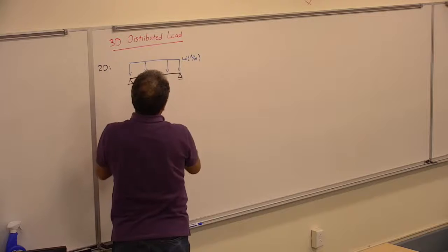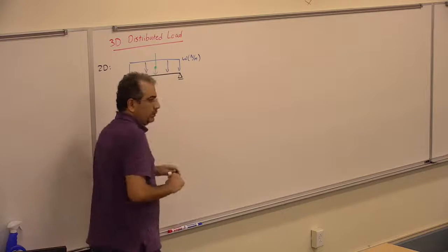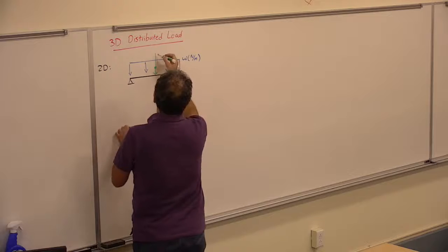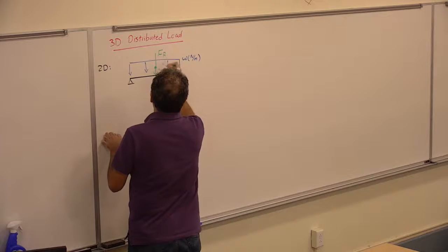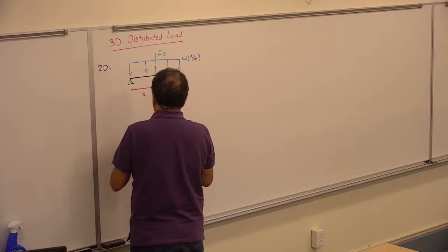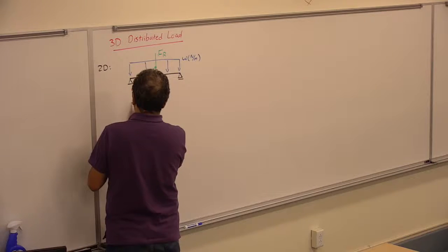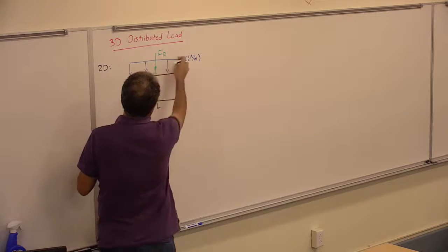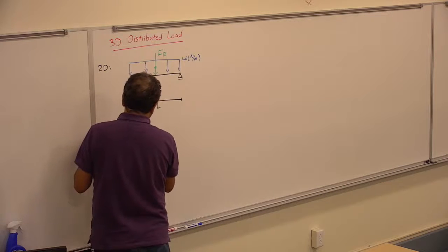So, for example, this is a rectangle. You know the centroid of that is here. So that load will pass through that centroid of that load. And the amount of that load, the magnitude of that load, was the area under the curve. So if I say, okay, this is the R, and this position is the X. X would be the X of the centroid for the load, which for the rectangle would be half of the total X.